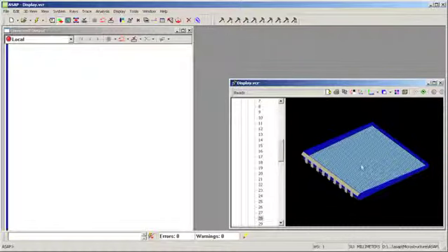If we suppress the top surfaces of the display, as we've done here, we see an array of 2,500 bumps molded into the floor of the waveguide. Refraction and reflection from these bumps directs light out of the top of the waveguide to illuminate the display. These bumps are microstructure.